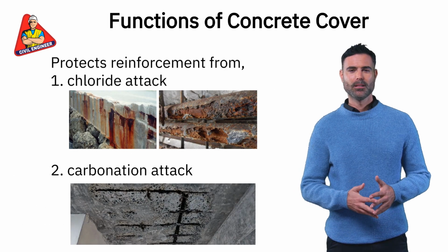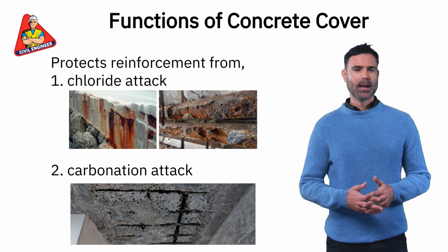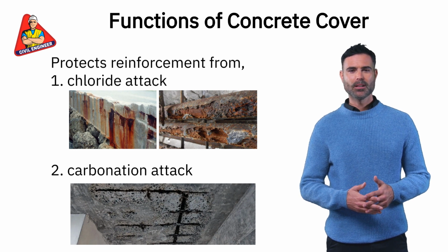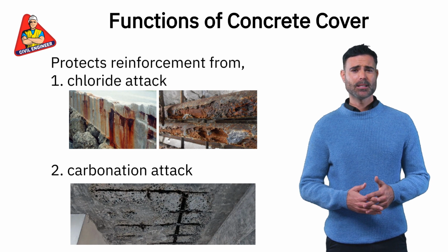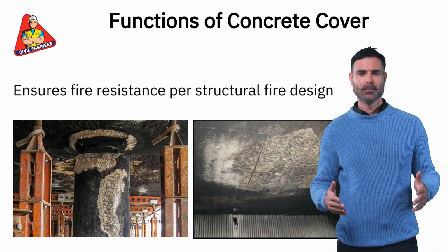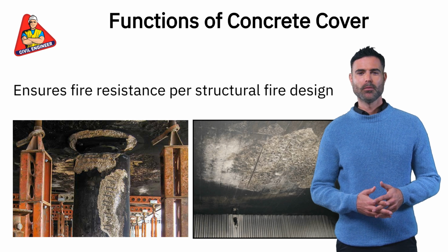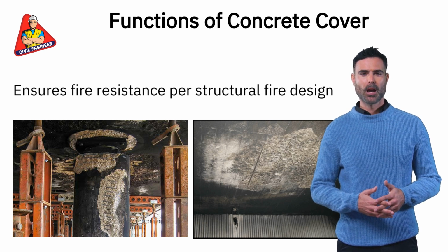Concrete cover serves several interdependent roles. It acts as a physical and chemical barrier against environmental agents such as CO2, O2, moisture, and chlorides, thereby delaying corrosion initiation of steel. It contributes to structural fire protection, where minimum cover depths are required to delay thermal transmission and maintain residual strength under fire exposure.